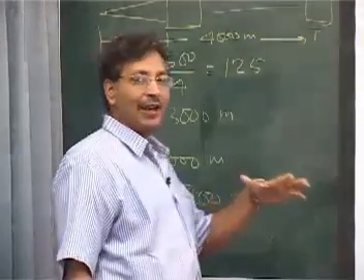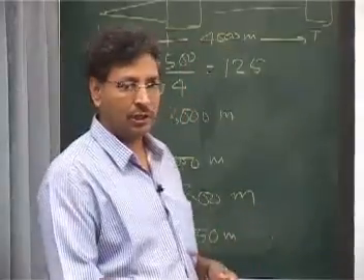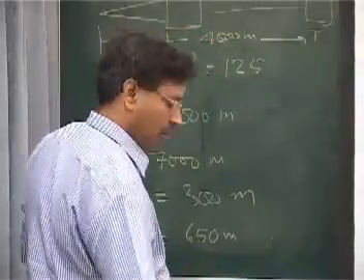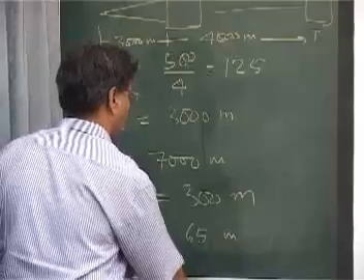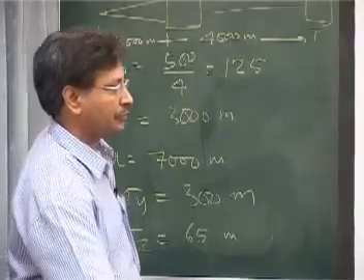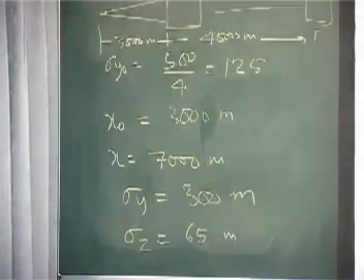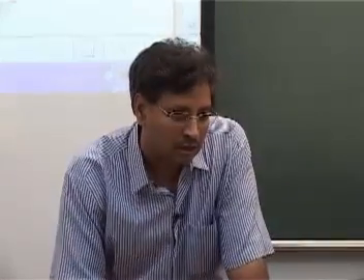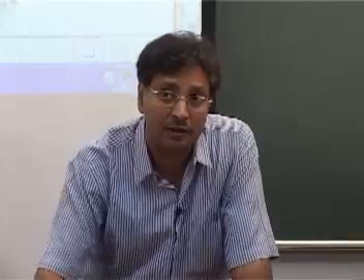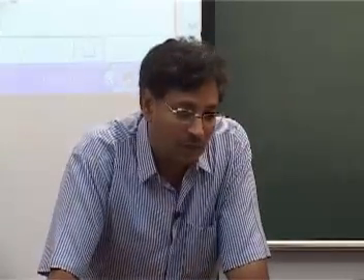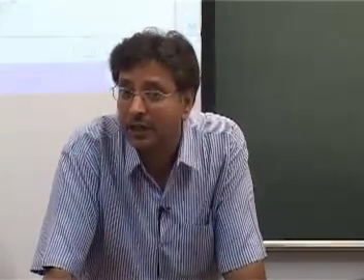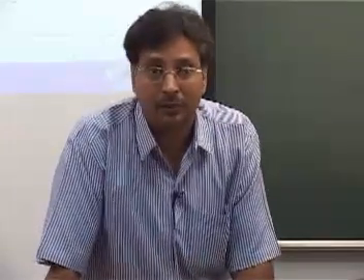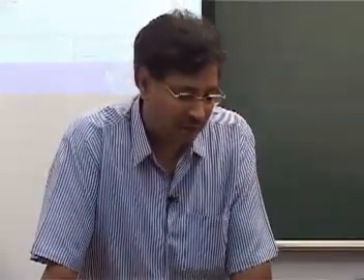And how can you quickly calculate the concentration? Oh, okay, all right. I agree with you. What was the H? 30 meters, and U30 is given to you as 4 meters per second. So you apply the same formula, identical to what we did for the Mathura refinery. Okay, how much does that come out to be?